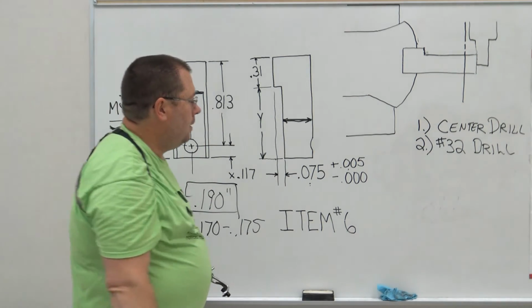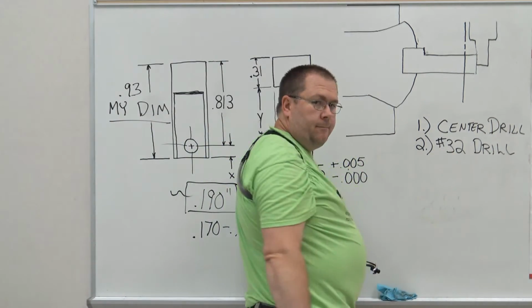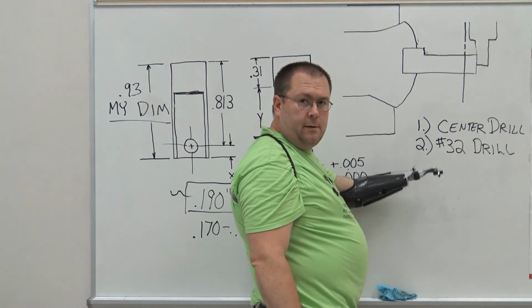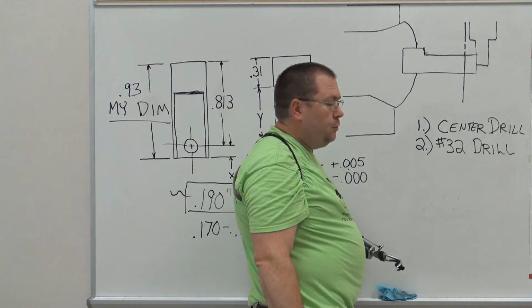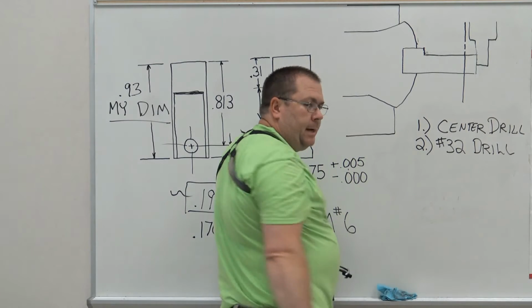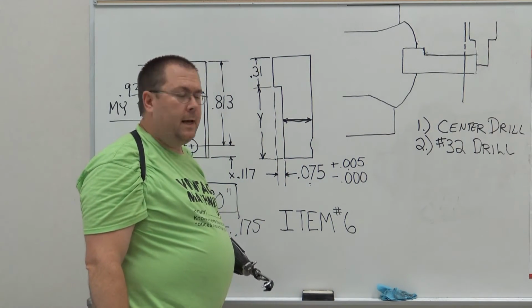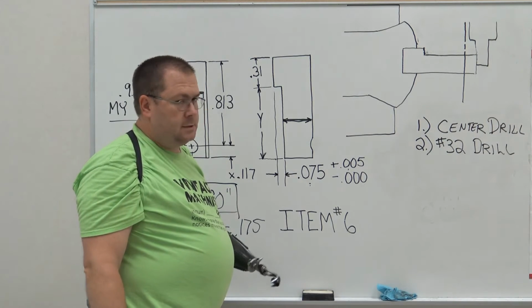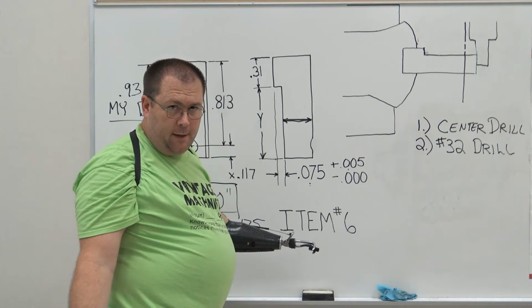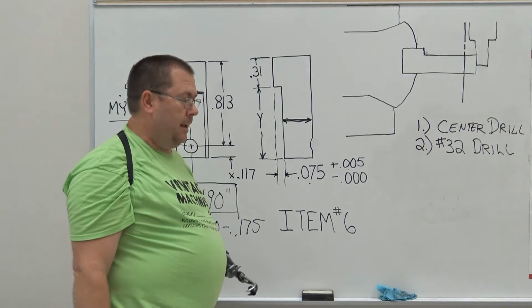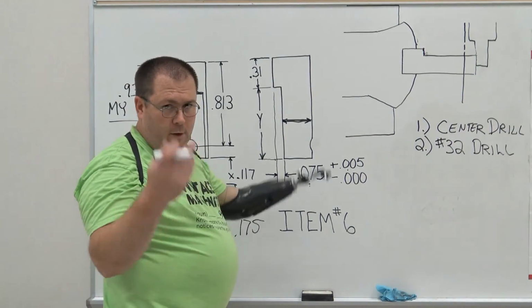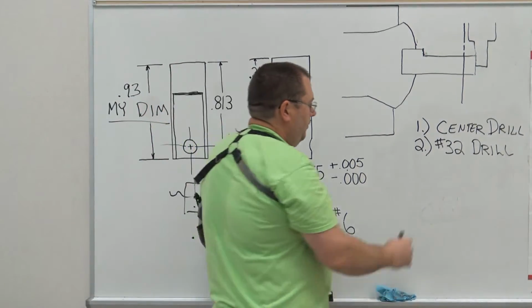Okay? RPM calculation. Remember, this is tool steel, so 4 times 50 is 200 divided by 0.116. Okay? Still up in the 2,000 RPM range if I round and do kind of the math in my head. So we're going to run at max RPM.